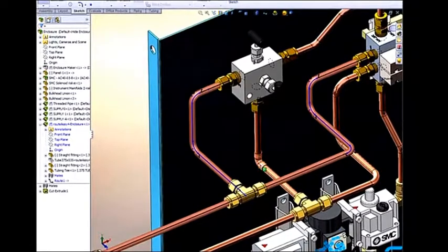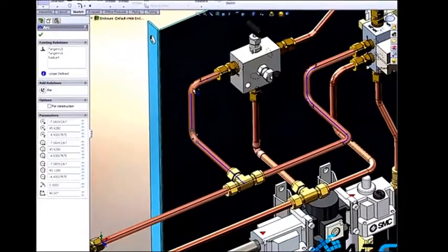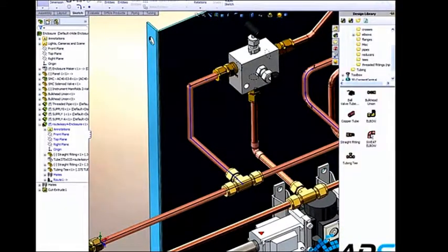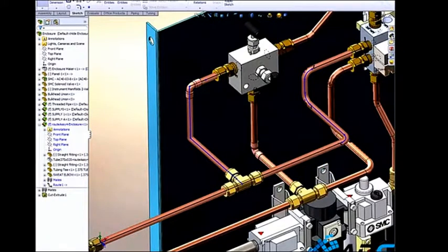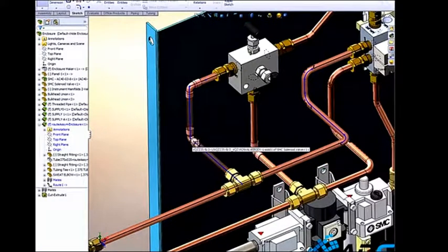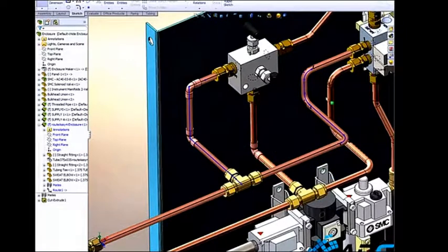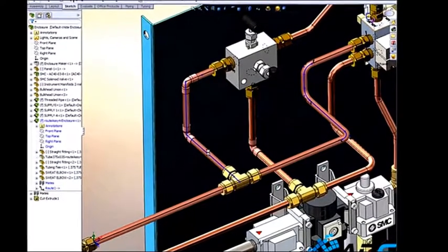Now just to change things up, you'll notice that there are some sweat fittings in the corners. SOLIDWORKS is very flexible, allowing me to use bent pipes, or in this case, we'll just delete the bend information off and use a sweat fitting by dragging and dropping. Place 2 of those into our design. One of the benefits of SOLIDWORKS routing tools is that behind the scenes, SOLIDWORKS is always trimming up the pipes to be the appropriate length for manufacture.